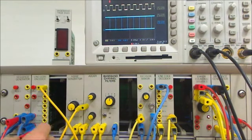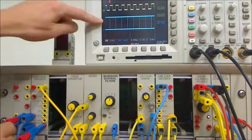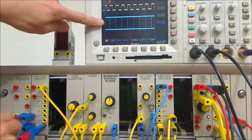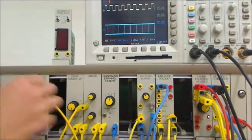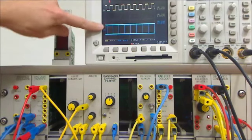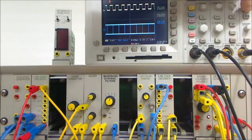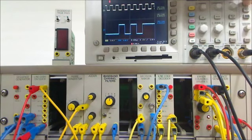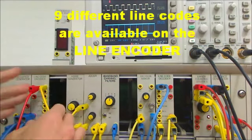and as well we are viewing the digital data output from the sequence generator. Removing the probe, we have a look at the output of the line code encoder, which if I single shot it, you can see that it is a plus or minus 2 volt level shifted signal.